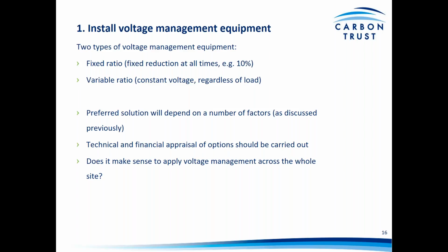So these can be installed downstream of the main electrical incomer, and can be a useful alternative to the site-wide approach if a site survey determines that specific systems, say for example lighting, can benefit from voltage management, but the rest of the loads on the site are voltage independent.